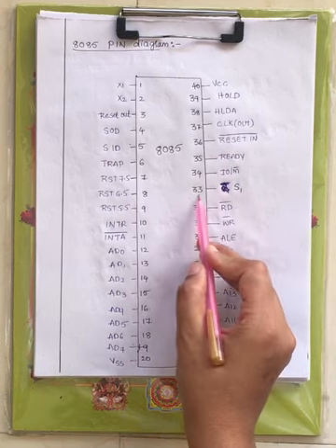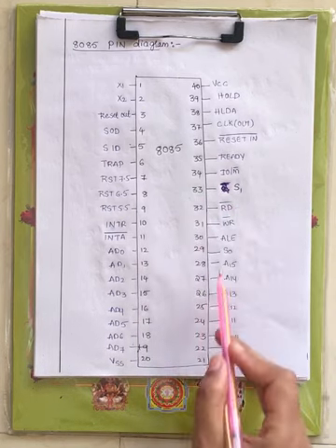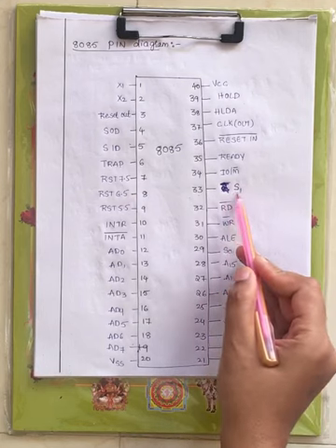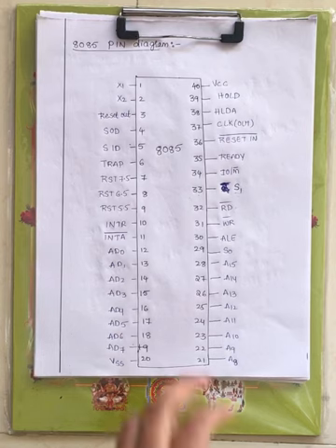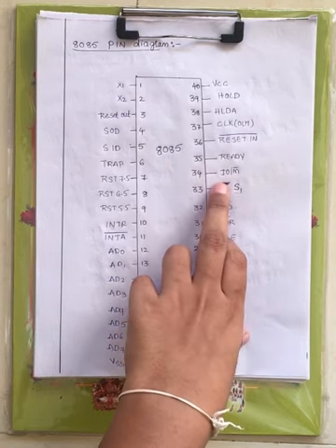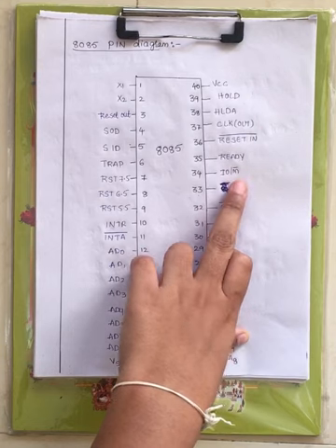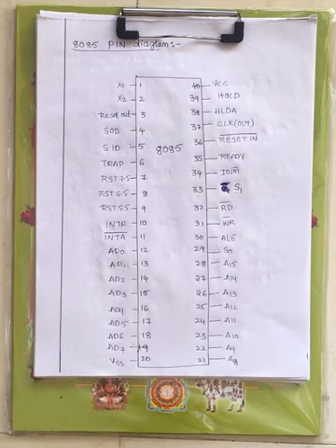Now at the 33rd pin you have S1. We have status signal 0 and status signal 1. Based on the inputs to S0 and S1, a particular operation is performed. You have a table for that, we will see later. And at the 34th pin you have IO/memory bar, input output operation or memory operation.